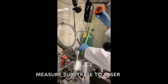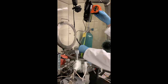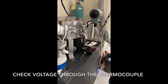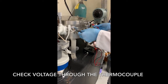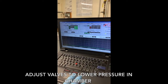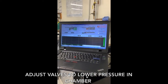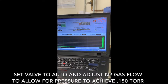The team then measured the distance between the laser and the substrate, and then the height of the laser, which is used later to calculate the angle between the sensor and the laser. The pressure inside of the chamber is then lowered to about 0.150 torr. An inlet of nitrogen gas is then adjusted to maintain this pressure.